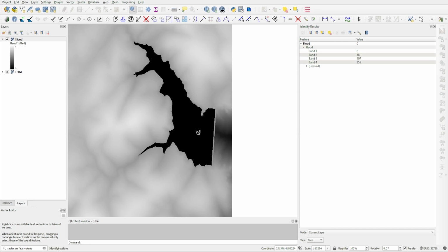And so you can see if I just click randomly somewhere in the layer, the values will change. And we don't want this. We want all of these values to be 0 or just have the same value here. So this is very simple to solve. We just need to re-export this layer and then re-import it back as a raster